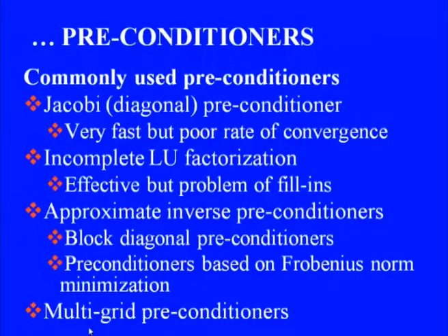And in the end I would like to mention this popular, very powerful preconditioner, multigrid preconditioners. Later on we will see that the multigrid algorithm can be used as a very efficient stand-alone solver, but there are certain situations wherein instead of a solver we can use multigrid as a preconditioner to a Krylov subspace algorithm, and the use of multigrid with the Krylov subspace algorithm results in what we call an optimal method, for which the number of iterations required is independent of the system size.